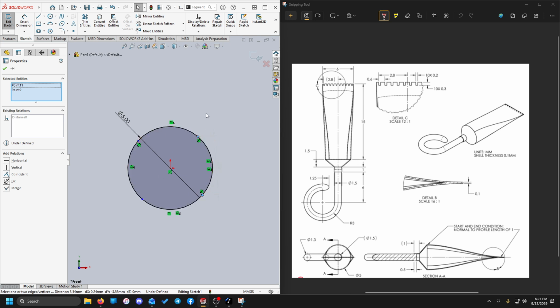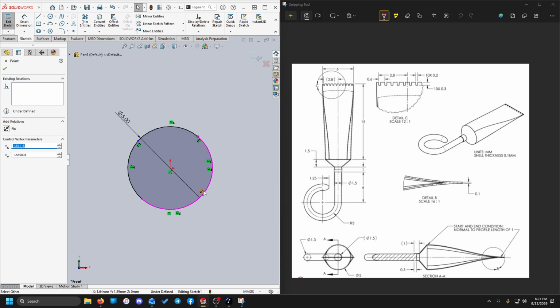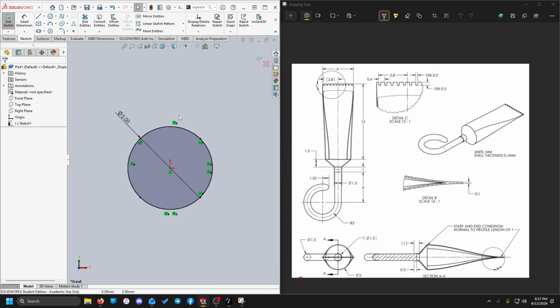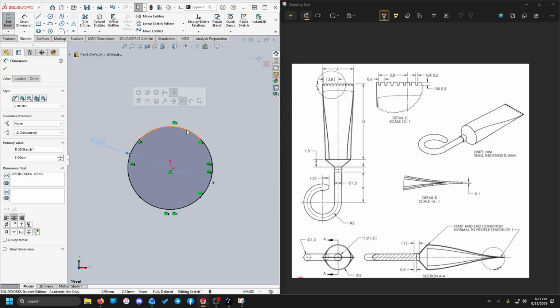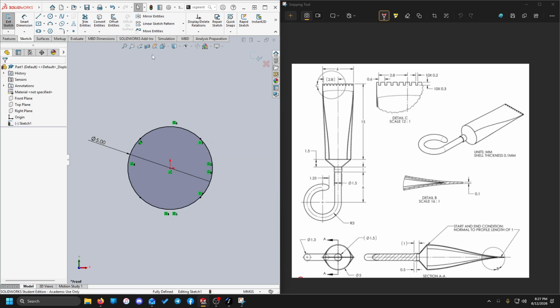And from all of that, it looks like it's pretty symmetrical with itself, and that it's got points sort of up. Sort of, what time would that be on a clock? Sort of at like the 1:30 mark. So for that, we can just grab these 2 points, and if we set them to be vertical with each other, that sets our rotation so that our quadrants are sort of in the northeast, southwest portions of the compass. Cool. So there's our first sketch.